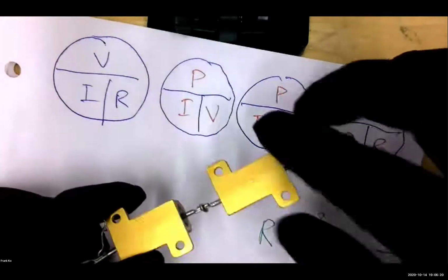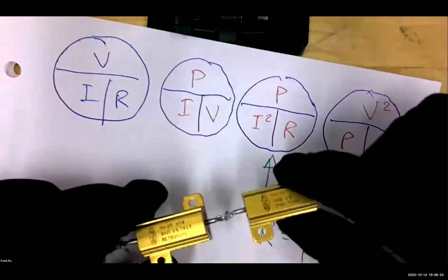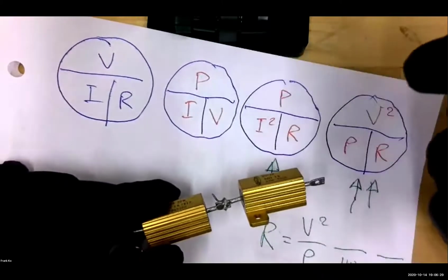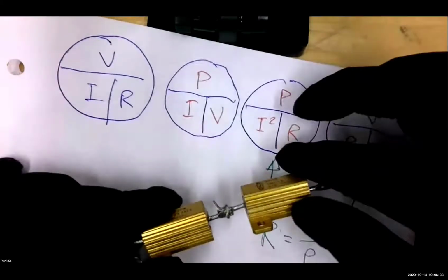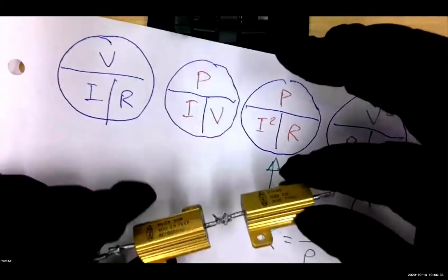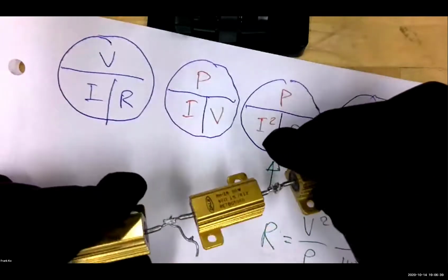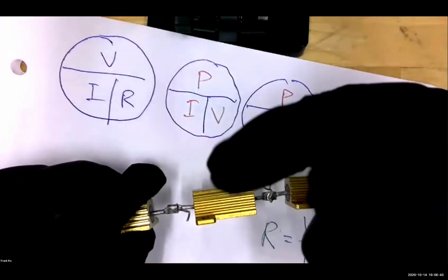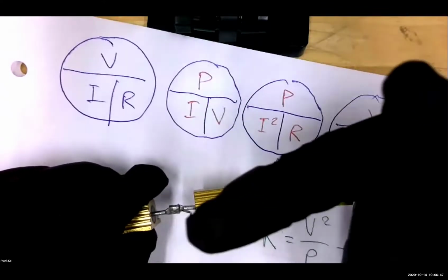This is an aluminum body, so aluminum dissipates heat really well. And they're finned, just like the fins of your motorcycle engine or the fins that you find on a gasoline-powered lawnmower. They dissipate heat really well. Well, if they put the fins on the body of this resistor, it'll dissipate heat pretty well. Guess what? It'll dissipate heat so well, it will melt the latex or the nitrile of your gloves. It will burn your fingers.